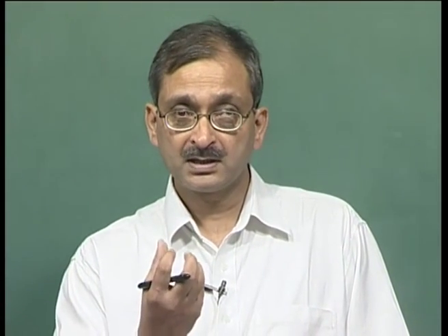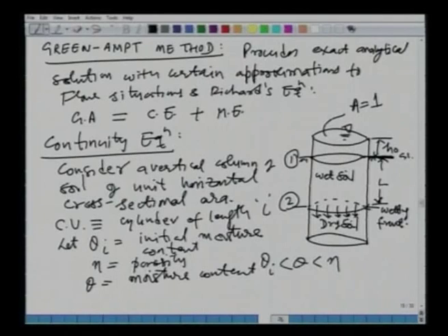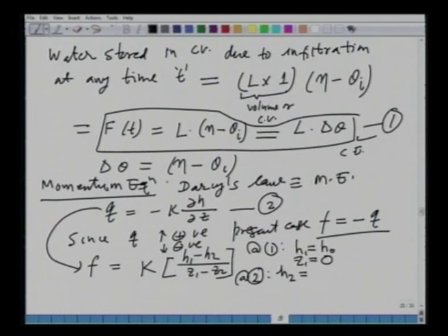One is the suction head and the other is the gravity head. Water is getting sucked into the soil due to the suction forces, and let us say the suction head is psi, and it is because of the datum head which has a length of L. Our notation is such that our positive direction is upwards. So your H2 is equal to minus psi minus L.